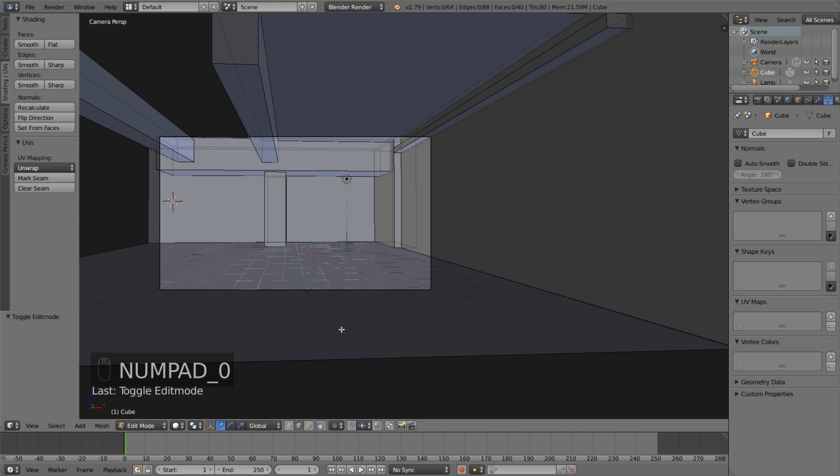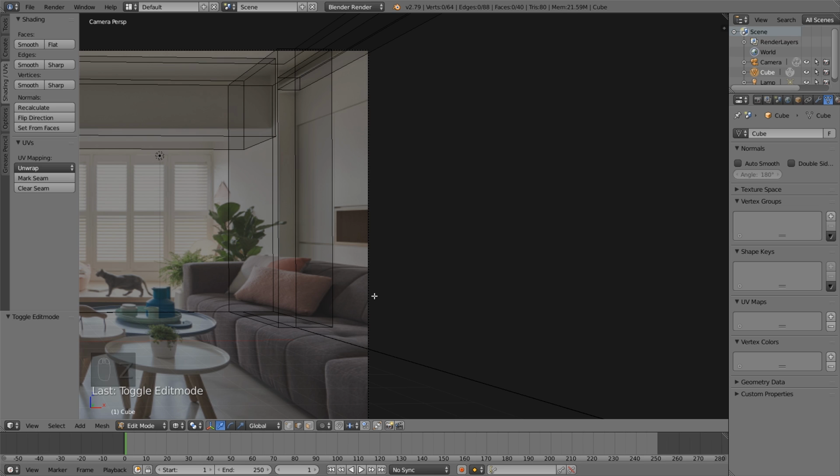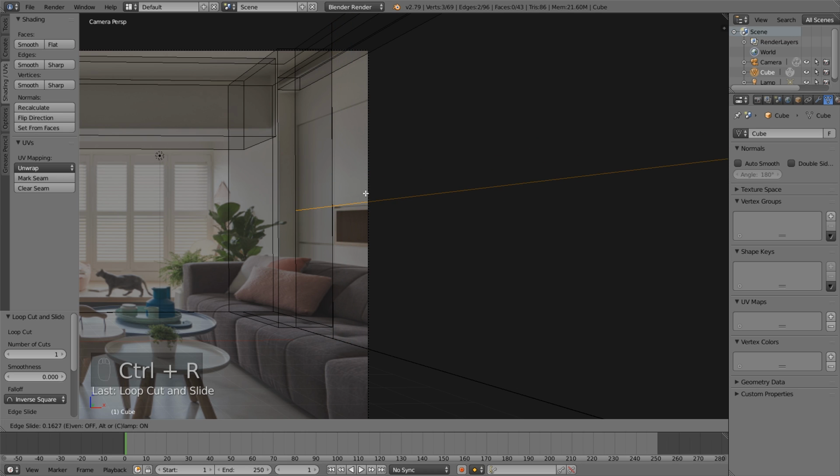So to do this, I'm going to put the cuts while in the camera view here. So I can go Control R, drop in a cut right there vertically, drag it down to be right to the outside of the box you see here. Now we're just going to have a cut on top. So Control R, slide it down, and Control R, slide it down.